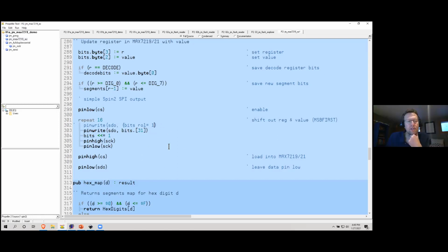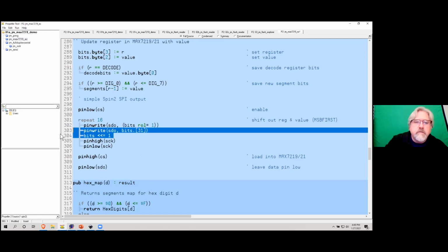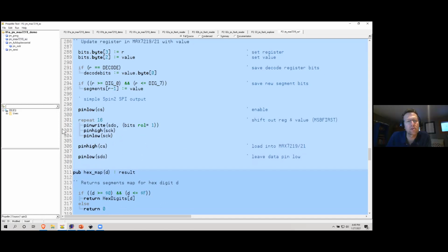John, I have a question. This is really a bit banged SPI. Yes, it is. What is the rate at which this occurs? And how do we know the device it's talking to can speak as fast? That's a great point. The nice thing about SPI is it's really fast. I run at 200 megahertz. That's just my choice.